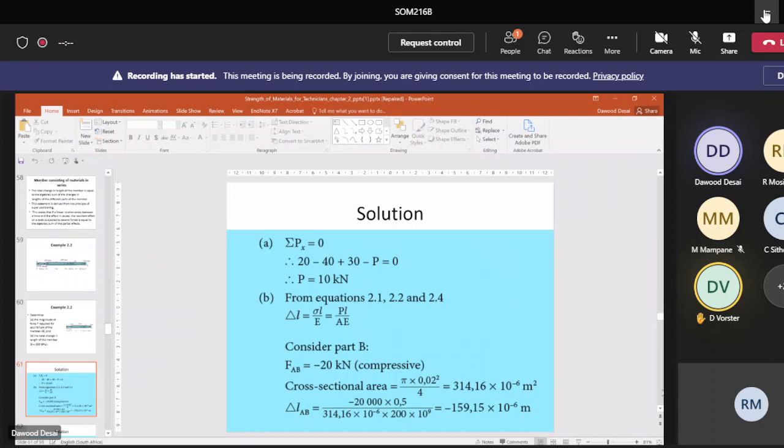Now the forces: upward equals downward. The load W must be equal to the summation of the force in each member. It's not equal like the one we just had. See that? That's the important rule there. And the second one, like I said, must be opposite. It's not adding each one. The change in length of member 1 will be the same as the change in member 2, will be the same as member 3. So you can solve for any one. It's also equal to the total change in length.